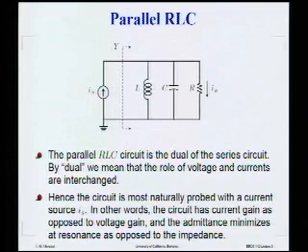Now, if you were a mathematician, you would just show this slide and say we're done, because a parallel RLC circuit is the dual of a series RLC circuit, and we don't need to rederive everything. It's true. It is the dual. Currents turn into voltages, the inductor turns into cap, and so on and so forth. But it's probably good to go through and derive the results quickly, because the intuition between a parallel RLC circuit is very different.